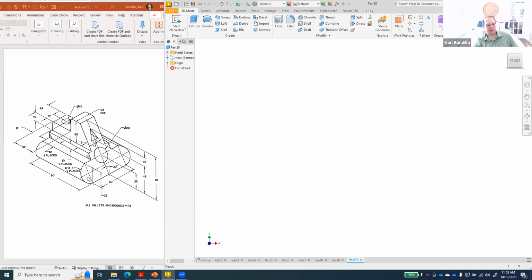So what I would recommend to do with these kind of shapes is that we draw something that is vertical, extrude it, and then we'll just cut the surface to look like this. The reason I would suggest that is that all the height measurements and everything is given as vertical heights, not heights within the plane. So it's going to be easier to do that.